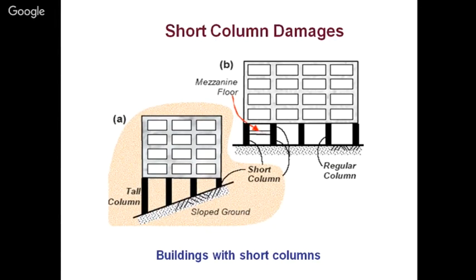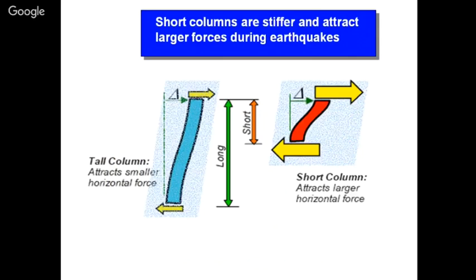Buildings with short columns, you are supposed to keep the things as per the analysis. If you are having a slender column, accordingly you are supposed to provide the confining reinforcement as well as longitudinal reinforcement.